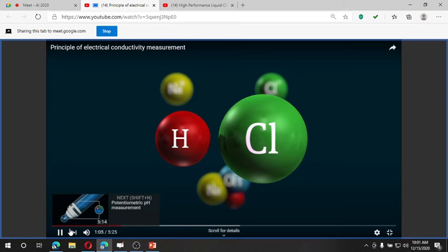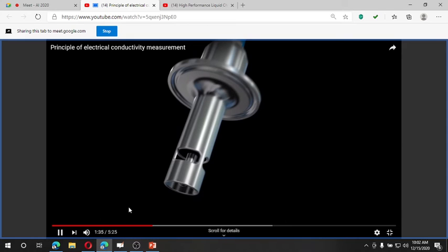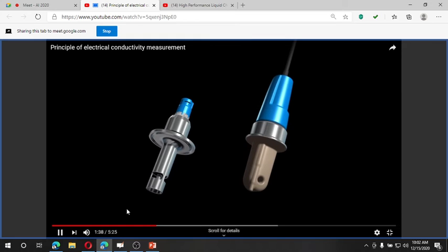Okay, so the idea was first proposed and developed, giving the first conductometer for electrical conductivity by using an alternating current to measure electrolytic resistivity for the first time. The physical unit of electrical conductivity is Siemens per meter. To determine the value, the so-called conductive and inductive measuring principles can be used. In the conductive measuring principle, two electrodes are positioned opposite from each other. An AC voltage is applied to the electrodes, which generates a current in the medium.